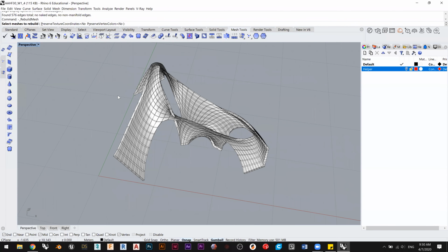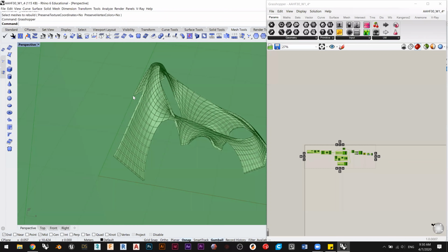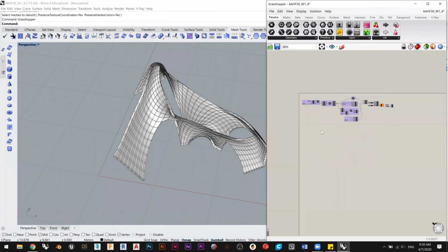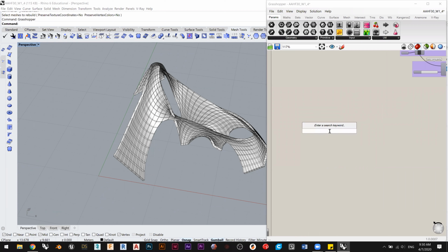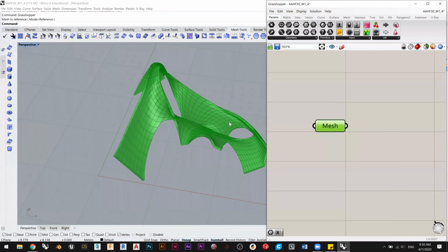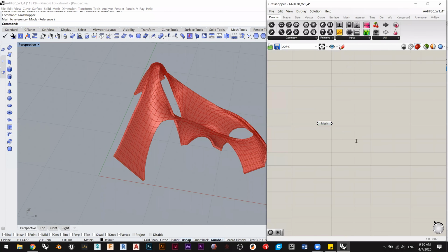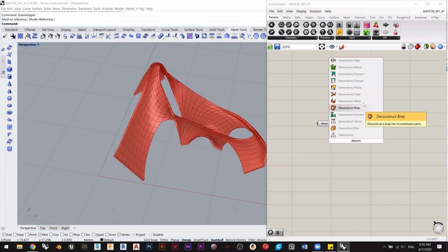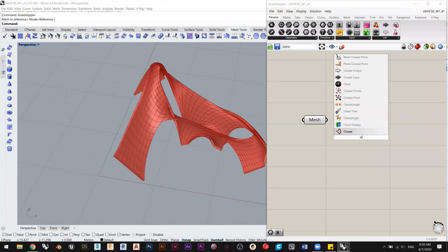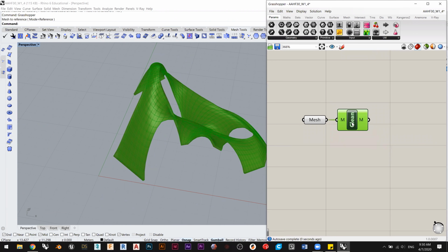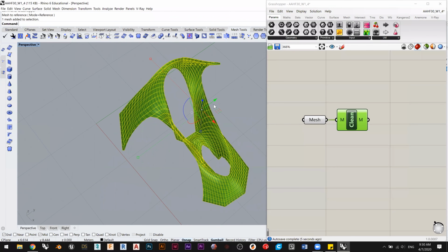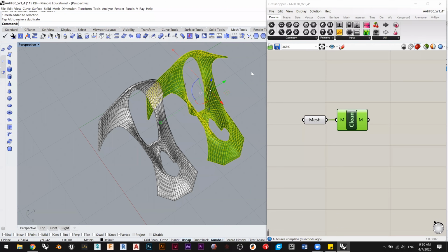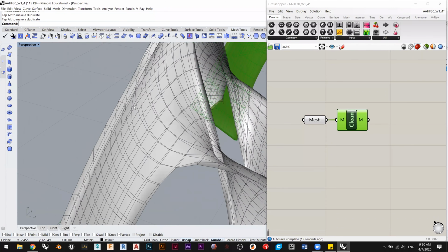Okay, if this happens, then what I prefer doing is I just run Grasshopper. I reference in that mesh, the broken mesh. Set one mesh like that. I deconstruct it, or even let's just try clean, combine and clean, and bake out the output of combine and clean and just see what we get from it. Still broken, what the?